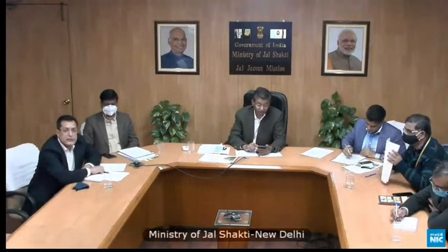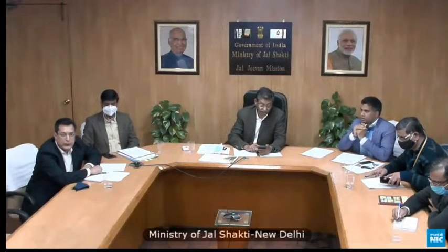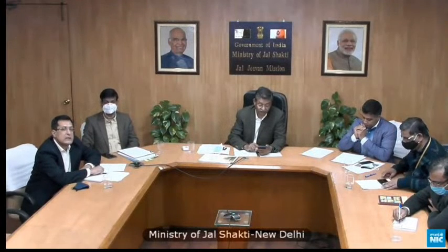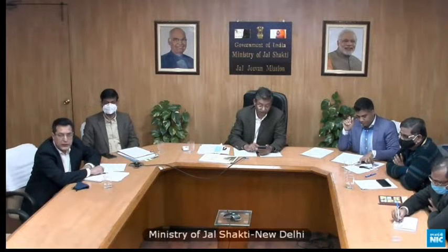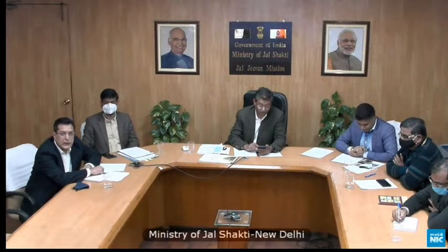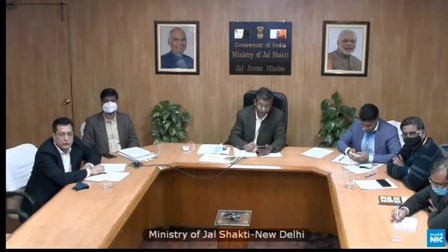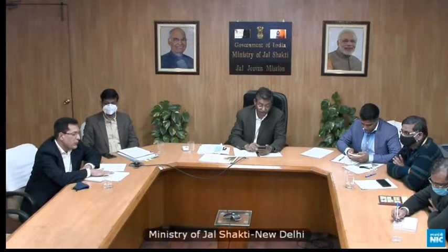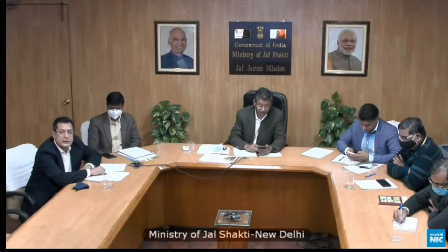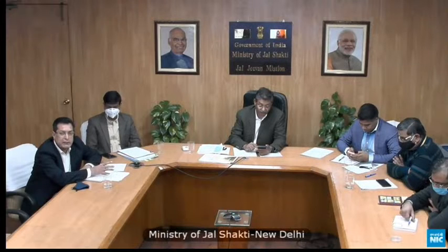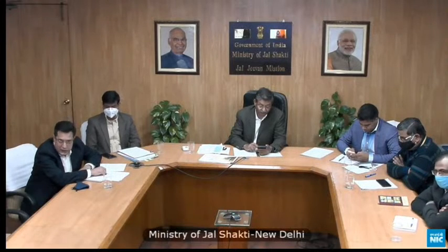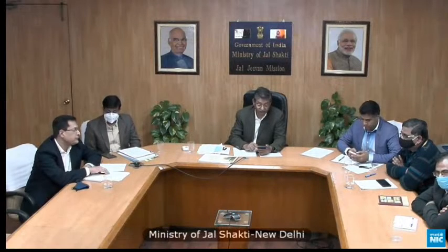The question regarding design software: I talked about two components. One component is the GIS mapping. For GIS mapping, we have QGIS software, which is freely available on the web. Anyone can download it and work with it. It's a very simple tool, and with a few days of training, we can do those things. When we talk about design software, since village infrastructure is a very small scheme with limited pipe nodes, we can use EPANET. EPANET is also available free on the net. So these software can help to plan or design the village infrastructure scheme. Thank you.